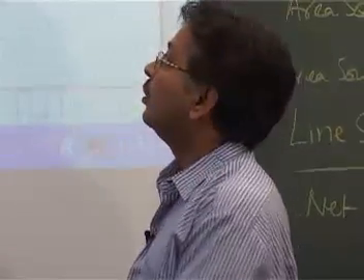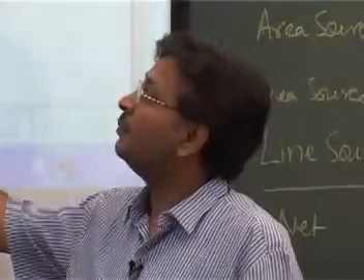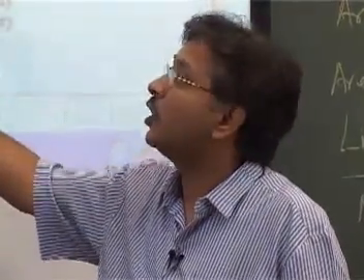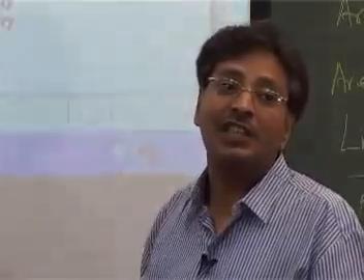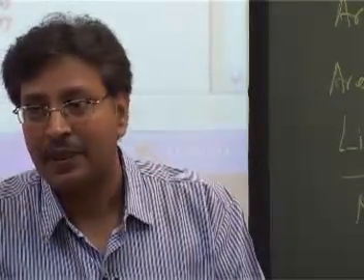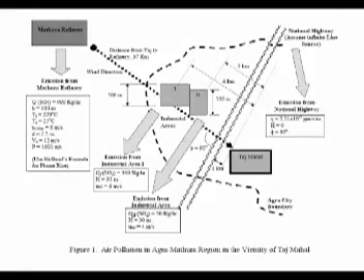If we can do something about this, so that the emission is brought down, convert the processes here, where we are using coal and oil, to something more like CNG. Sulfur content in CNG is zero. The moment you say you use CNG, because sulfur dioxide will come from the combustion processes, and you make them CNG, or 50% change them to CNG, this is gone. And you ask the Mathura refinery to control the emissions to, let's say, one third or something.